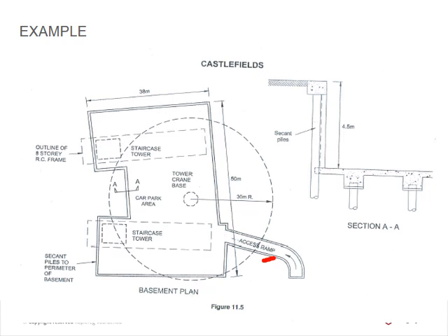I'm also not going to go through the method statement in detail, but you will see you've got your description of the works at the top. That's the one that you've just started, and then you've got your sequence, where prior to excavation works taking place, the following procedures must be carried out, and then you list the details of how to go about it.